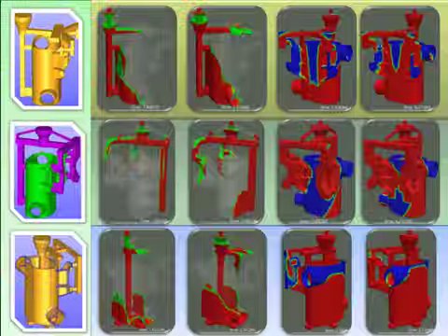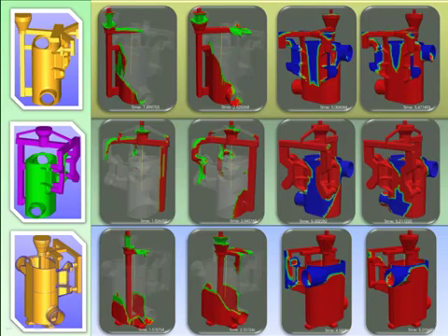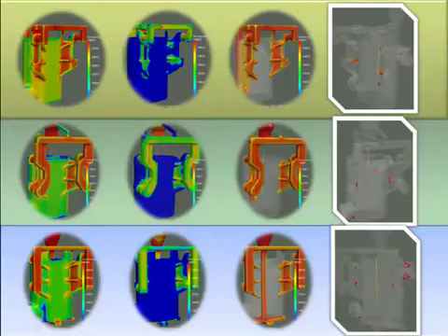If we check the metal flow, we can see the last one has the best balance, and the first and second are not so good, especially the second one, with a big problem of air entrapment and filling sequence. This is the solidification result, including temperature distribution, liquid or solid fraction, and also the shrinkage porosity, shown in the last image of each model. With this result, we can easily predict casting problems and defects. The simulation time is very short; all the solutions take less than 2 hours, including filling and solidification.